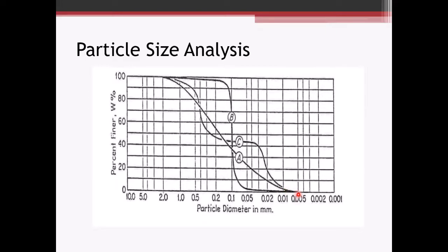So if you can envision a garbage bucket, which is filled with basketballs, volleyballs, softballs, golf balls, down to marble-sized particles. Basically, all the void spaces in there are taken up by the different particle sizes, which makes a well-graded material. And typically, the well-graded materials are going to have a high unit weight, higher shear strength, and then a lower permeability because more of the void spaces are taken up. And typically, New York State DOT Type 2 or Type 4 gravels for subbases for pavement and slabs are typically going to be considered well-graded.